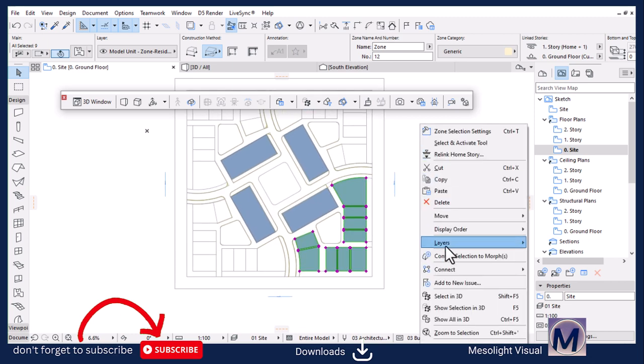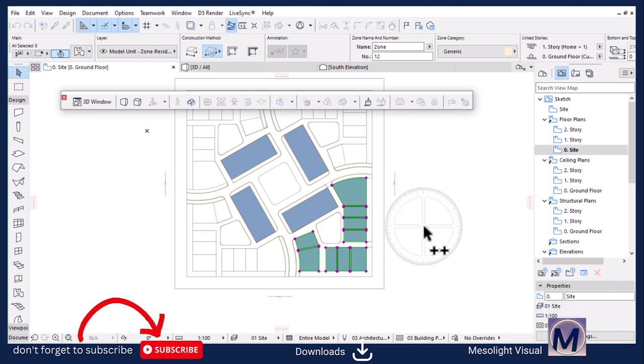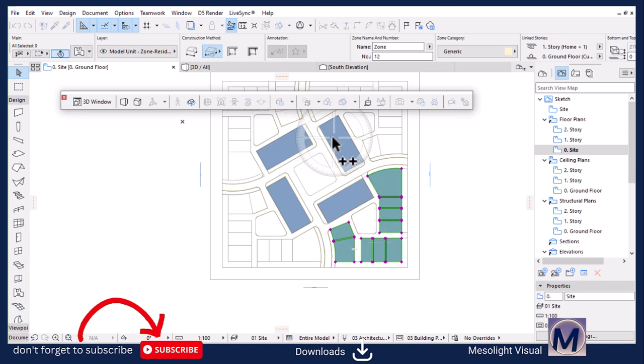So what I need to do is right click in the space and bring in the rotate multiple copies. I'm going to use the same trick like I did when I was doing the sketching. I'm going to find the midpoint of this area and then wait for the blue circle to appear, and then do the same to this side. We just want to determine the center of the whole plot.